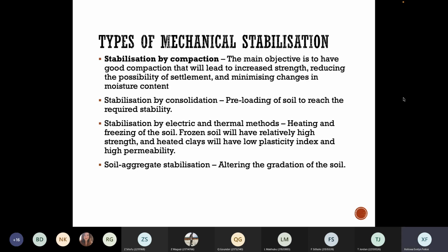But even before that, it's so difficult for you to mix it when you're determining the Atterberg's constants. That test is so not nice when you're dealing with clay soil, because the cohesive properties of clay are crazy. Therefore, they say you will heat it to minimize that property of clay as well.